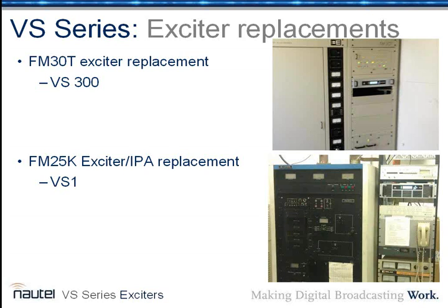And the reason for going with a 1 kilowatt over a 300 watt was? Like I said, the final wanted 318 into it, so we went based on that spec, and we don't like to push things hard. Sure. So we had the VS1, and since we were up against that wall, it's another one of those situations where we decided to put a coaxial switch in, and we can bypass the Harris and put the Nautel directly into an 8-bay antenna. And you could set up a preset so that instead of 295 watts drive, it goes to full 1400 or something. Yep, and we have that exact thing set up on the remote control that we can just dial into it and go. I don't have IP out of this site yet, but I will in about 2 months.